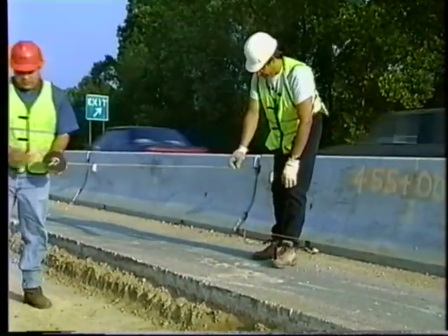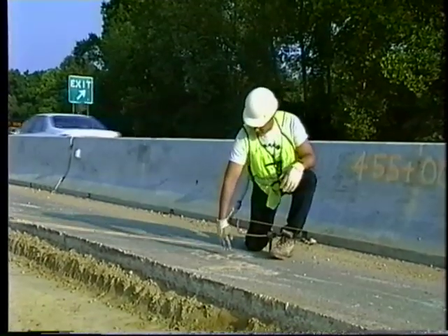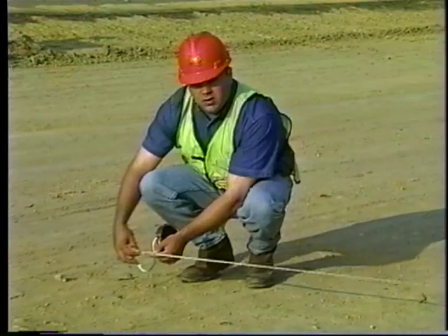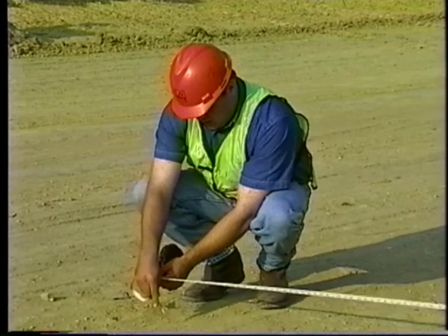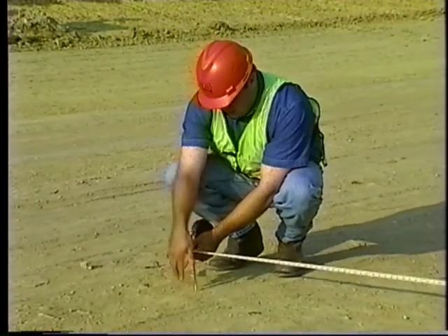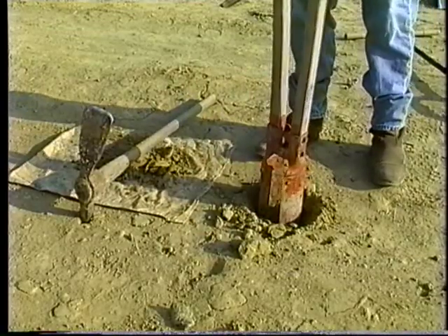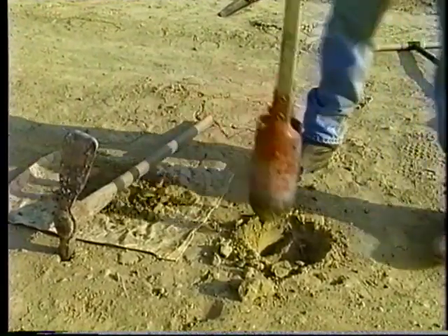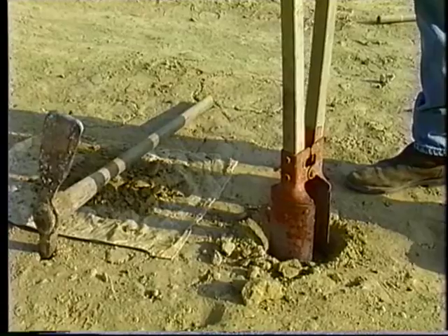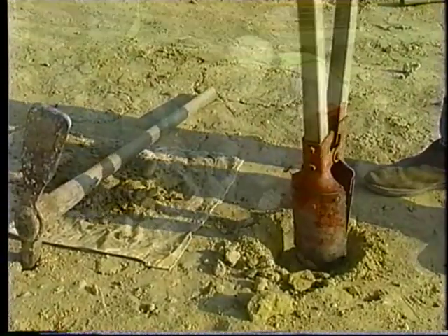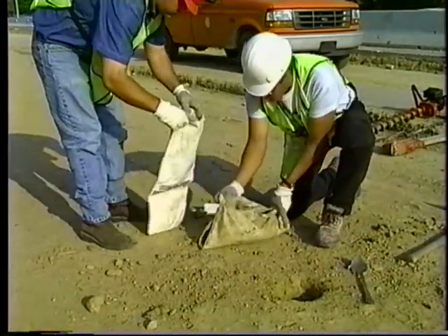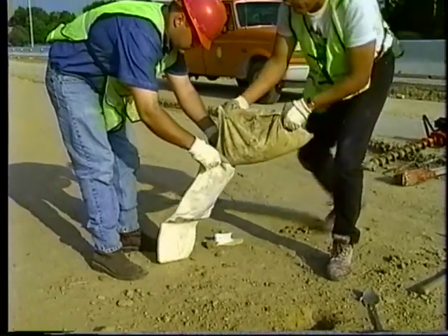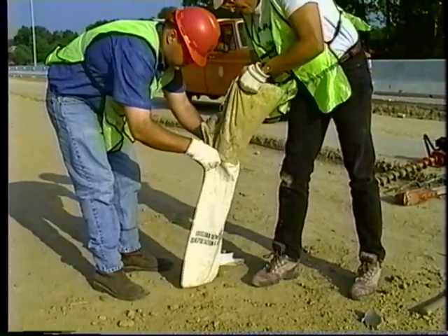See the material sampling manual for determining quantity and frequency of sampling. Samples are taken from 3 of the stations chosen at random, 1/3 from each station location. Dig each hole as vertically as possible and remove material to the full depth of the course. As with the other samples, the amount of material obtained may need to be reduced or another sample taken for the quantity to conform to the requirements of the materials sampling manual.